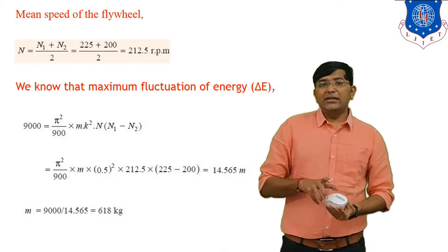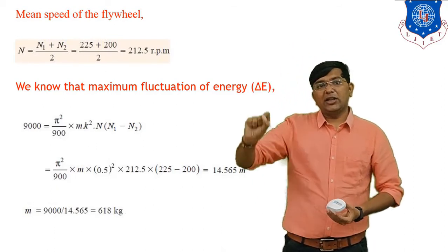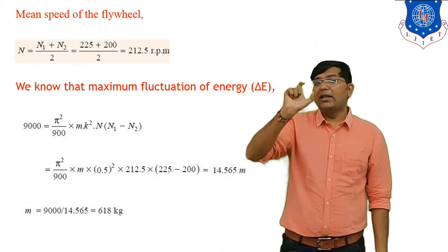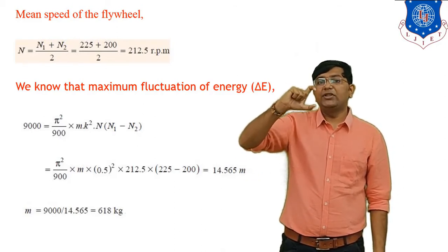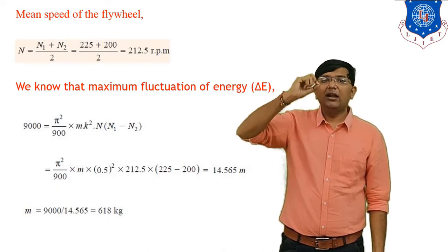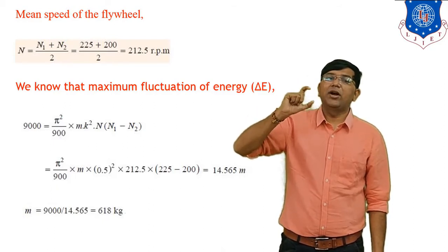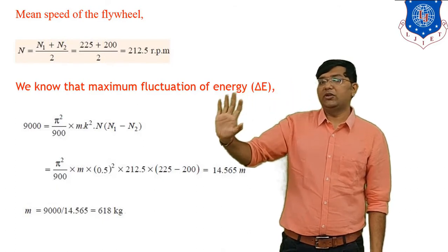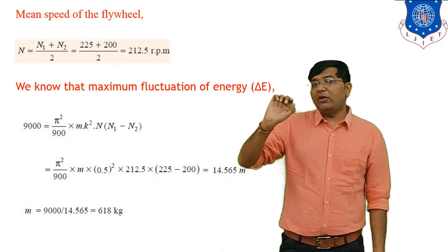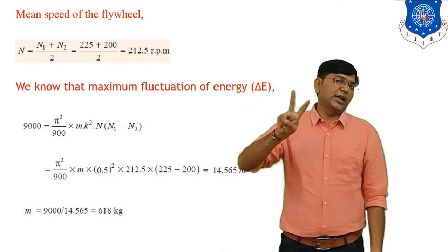So in E1 energy the crank rotates 360 degrees, but in E2 energy the crank rotates only through that portion where the punch comes in contact with the metal. Clear? And drills that metal. That is the energy required for the actual punching operation, that is E2. And in this numerical, the time required for actual punching is 2 seconds.